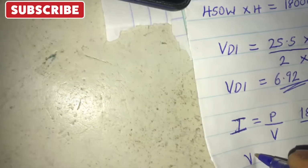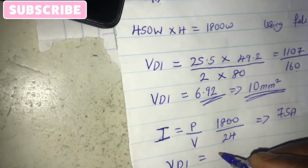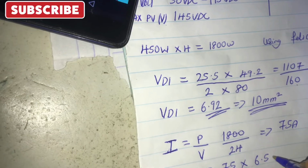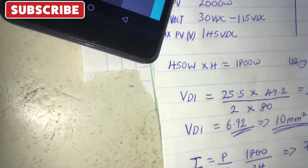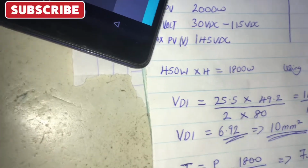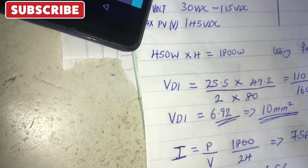So VDI, substituting this into our formula, we have current which is 75 amps multiplied by our length, which is 6.56, all over 2. Remember, when calculating for DC, you use 2, divided by our voltage, which is the battery voltage,